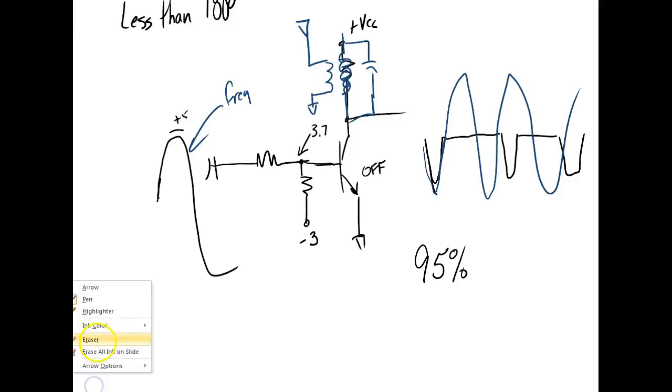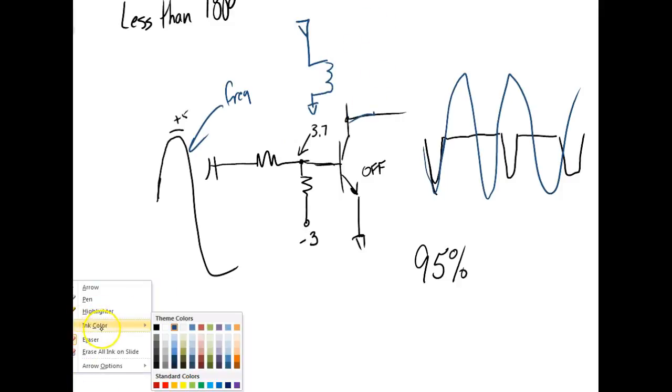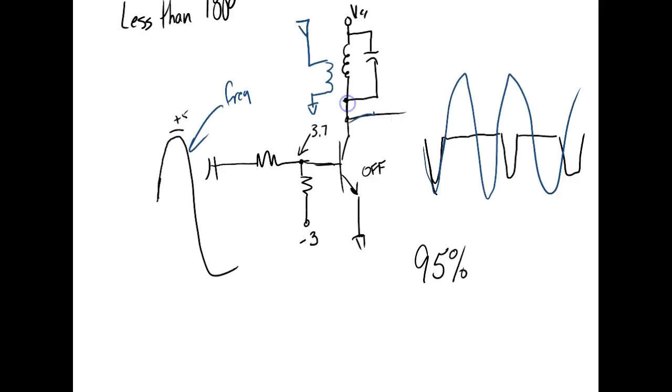Yeah, the inductor and the capacitor. Let me redraw it. So the resistor's gone. What turns into the load for the amplifier is a tank circuit. So this would be VCC up here. And then I would have an inductor that's actually a transformer too, serves two functions. And then we'd have a capacitor. So the inductor, the primary, is actually serving as the inductor for the tank circuit, and then your antenna is over here. There's a little transformer in there, a high frequency transformer.